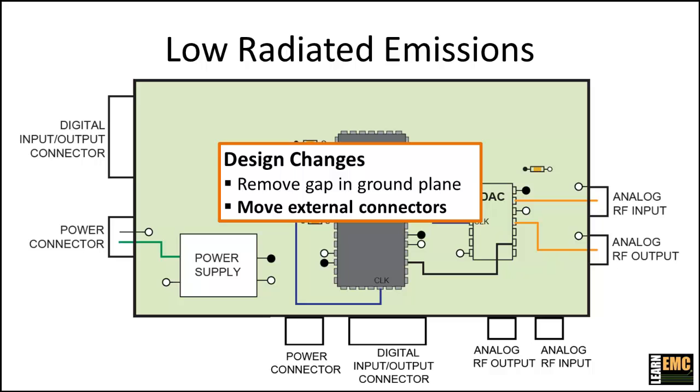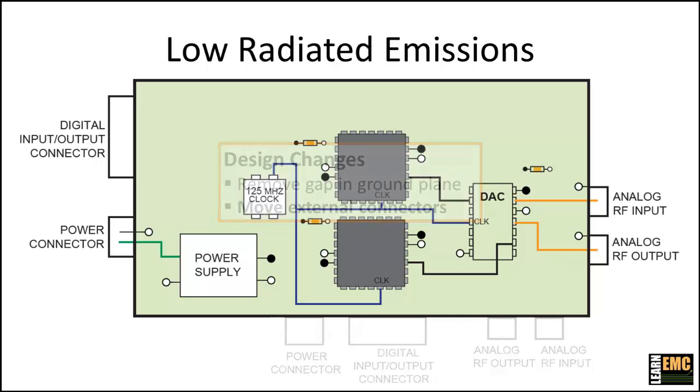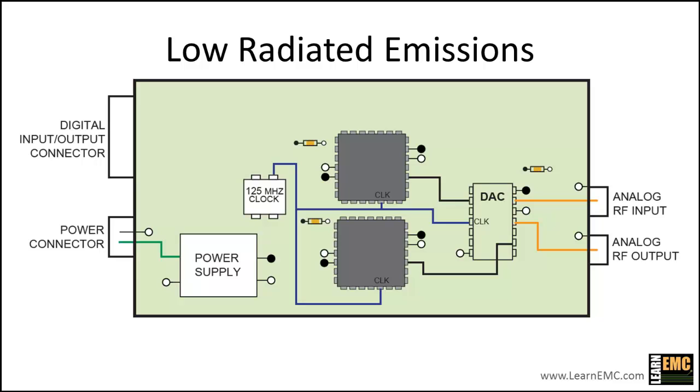There's one more potential antenna structure that we need to think about. Long traces carrying high-frequency signals can couple energy to other structures. For this reason, we want to try to shorten the length of all traces on the board that carry high-frequency signals. Another good reason to do this is that for short traces, the return current flowing on the ground plane has less opportunity to pick up noise due to common impedance coupling.